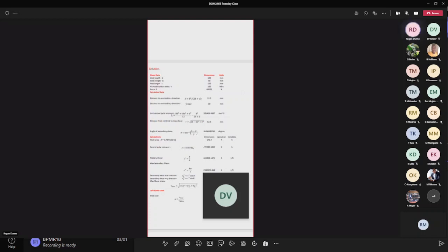J is the resistance to the twisting, where I would be the resistance to bending. If you imagine a ruler in your hand and you bend it, that would be I, the resistance to that bending. If you try to twist your ruler, J is the resistance to that twisting. That's the polar moment, like polar coordinates, because when we use polar coordinates, we're normally talking about circular motion. That's just a little add-on that you learn more about in strength of materials.